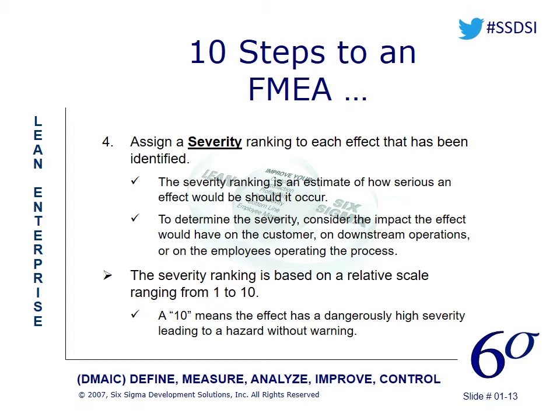Once you fill in all the other elements, again, input, failure modes, failure effects, causes, and current controls, then we come back and we fill in that severity ranking. And that severity ranking is related to the effect, the potential failure effect. So if my failure effect repeats multiple times because there are several causes for that one effect, and we'll talk about this, then my severity ranking is going to repeat.